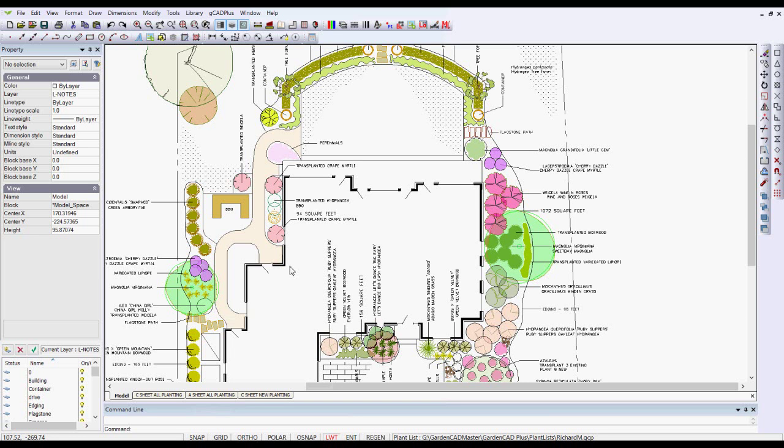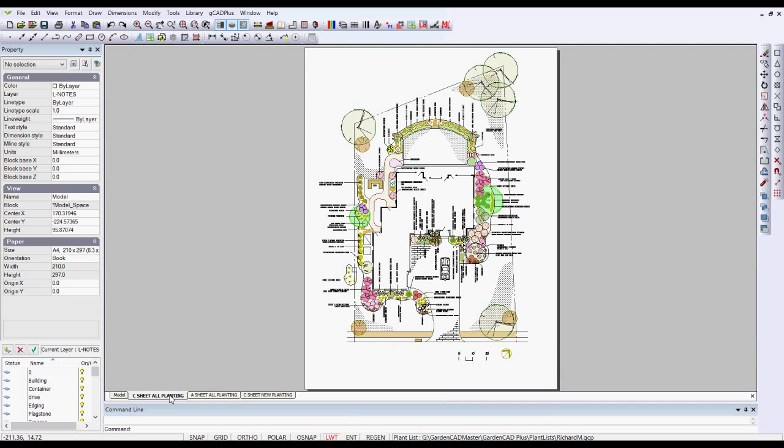If you've recently made the transition from drawing on a board to drawing with a CAD system, you may be a little puzzled by how you manipulate line weights. I have a Designer landscape design here for a site in the US, so our units are decimal feet. And when we print a design, what we'd like to see is line weights showing up. Now, in the status line, there's a show hide line weight switch, and I've turned it on.